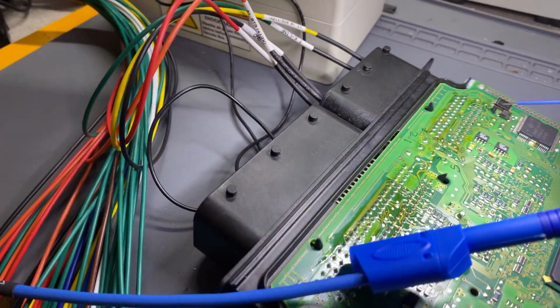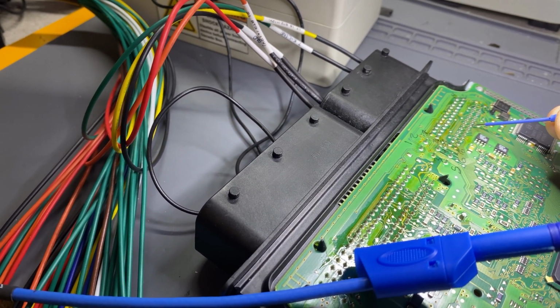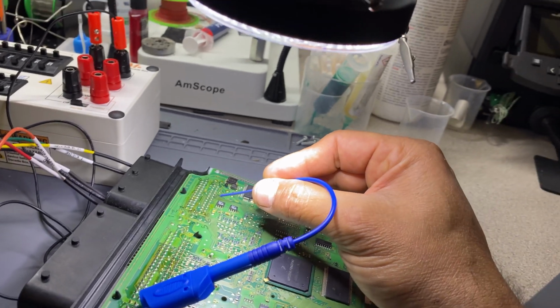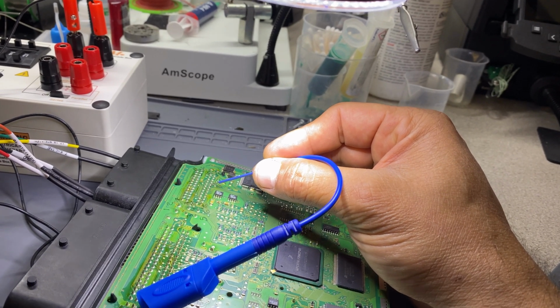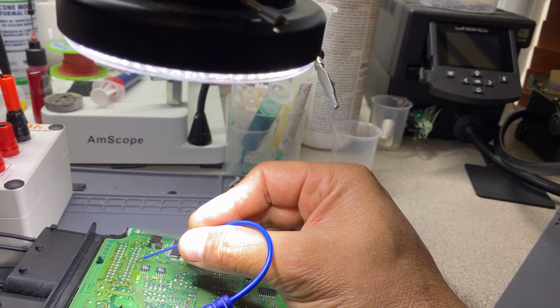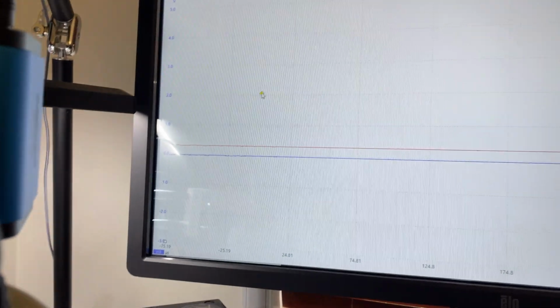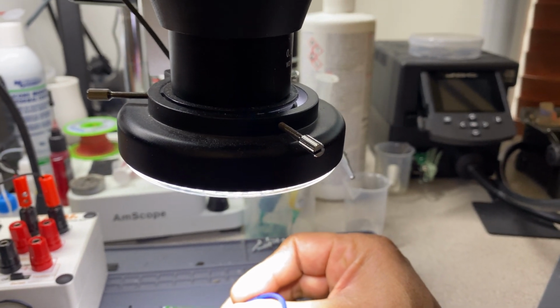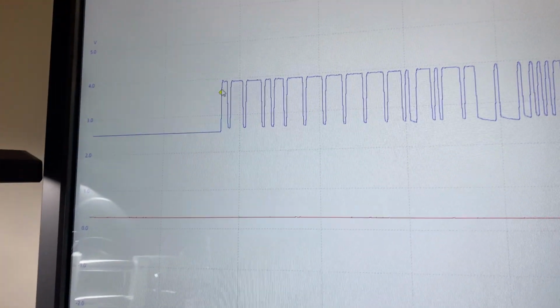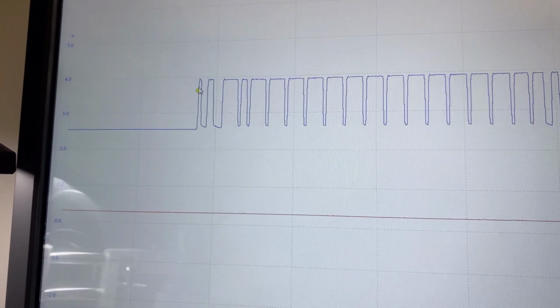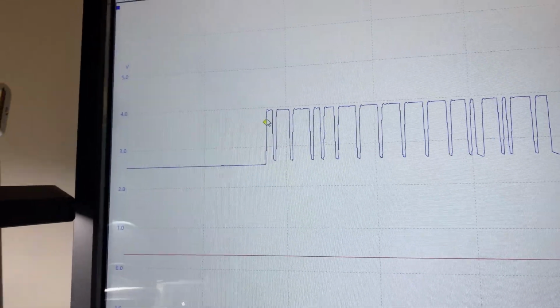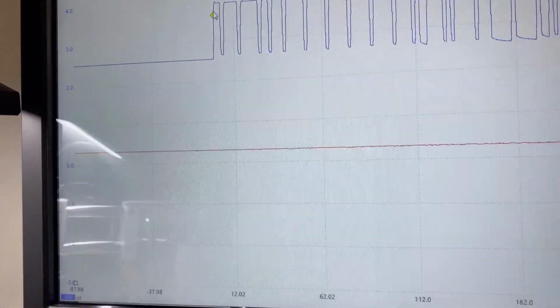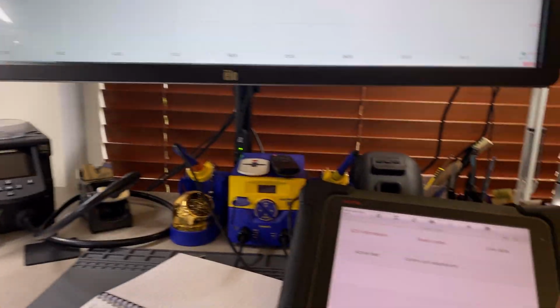It's a little hard to see, sorry. That one is not giving me anything. This one is. Oh yes, right there. It's not giving me anything because I'm using the trigger on the low side, and if I hadn't put a trigger, then it would read. Now, if I connect in here, we can see that signal is going from 2.5 to like 3.5 volts or so. Hopefully you can see that. So the CAN network is active and it's working. And obviously we have communication with the scanner because I can read the computer.